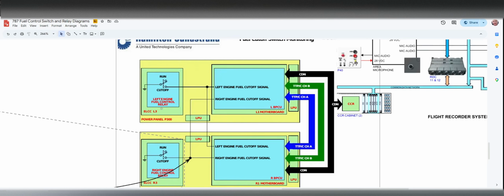The coils are oriented and need the correct polarity to push and pull the pin inside the relay in the correct direction. Reversal of that polarity will, if the voltage is correct, reverse actuate the relay in the unintended direction.